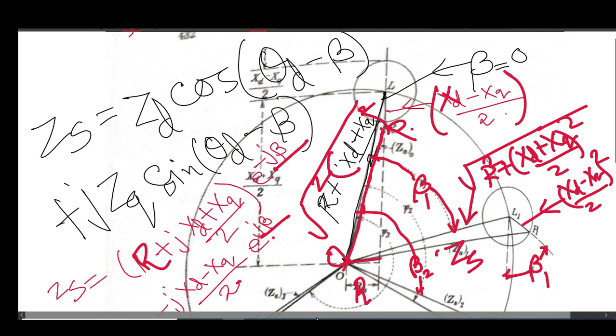So as it faces smaller reluctance, the armature reaction will be predominating, whether demagnetizing or magnetizing, because the reluctance of that path along the direct axis is very small.